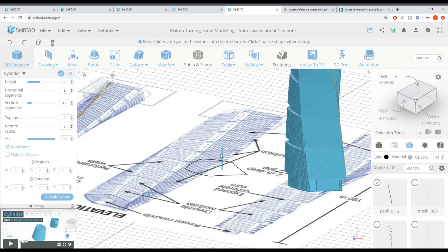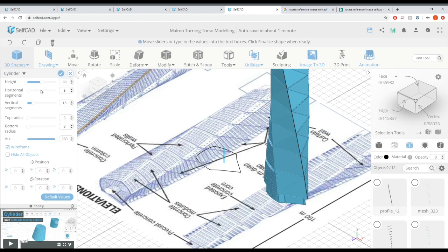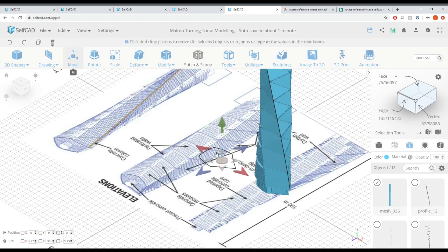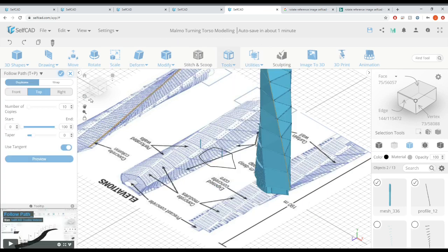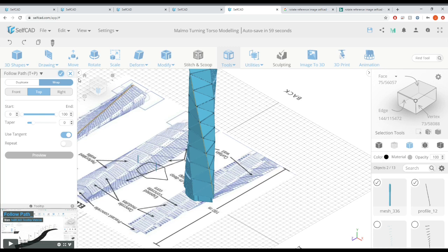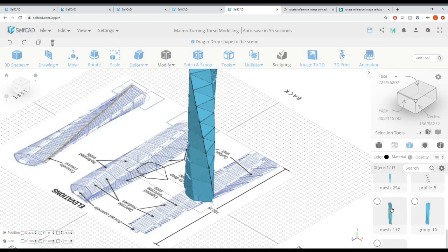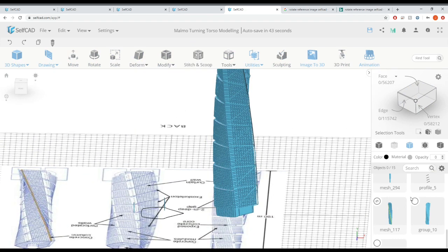And for this, we're going to create a cylinder. And the reason why I'm creating a separate cylinder and not using the one that we were using before is because I don't want the taper, because I want it to be the exact same width throughout. And similarly, we can use wrap again. And that should bring the structure to that sharp edge of the building.